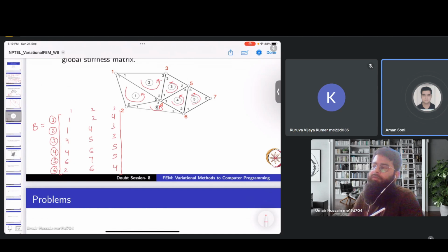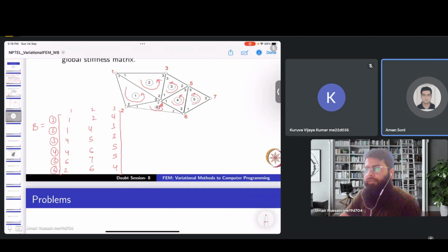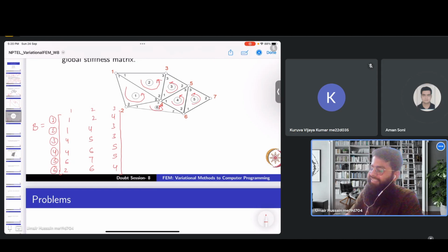So what you are saying is applicable regarding node numbering and the Jacobian. Yes, this is a good example, because my senior was asking me again and again how it is possible that such a fine mesh has a negative Jacobian value.